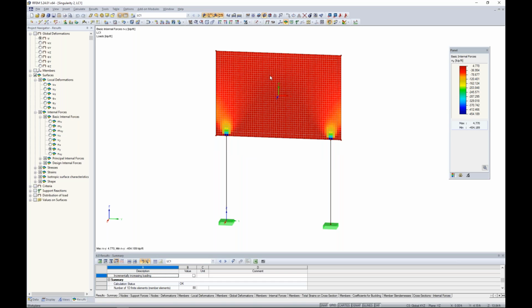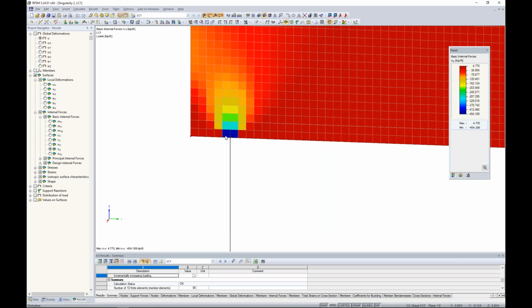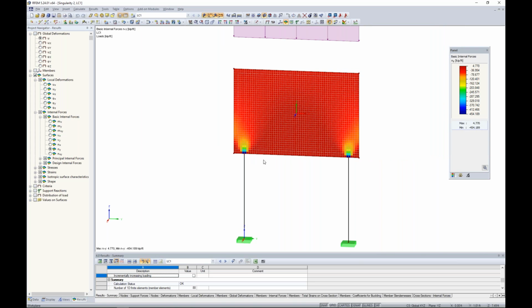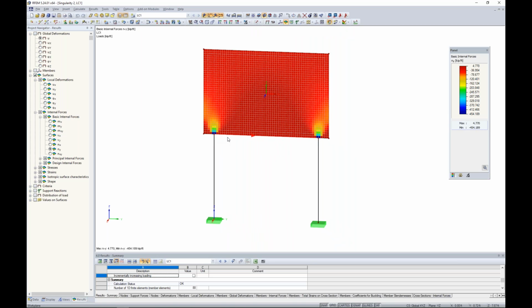forces, this is going to be compression and tension in this wall. We have extremely high peak forces here, you know, those singularities. We're seeing compression here at 454 kips. So this is definitely not ideal. So how can we see better load distribution over this area? This would be a situation where I'd say average regions could be helpful, but I think there's a better approach here. And that'd be to apply a rigid element for load distribution.